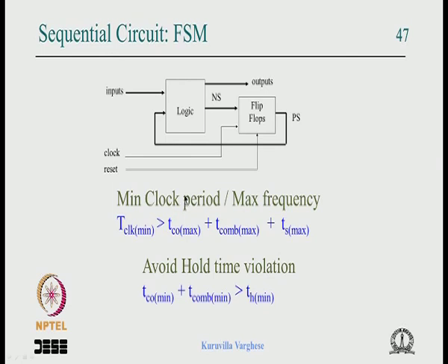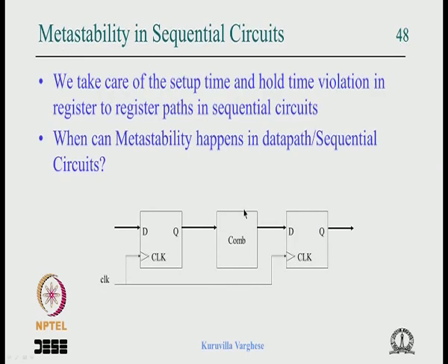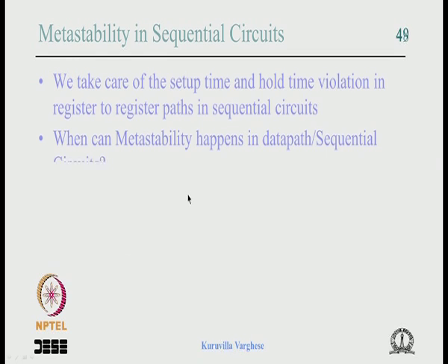Then why do we worry about metastability in a flip flop, because metastability happens only when they are violated? We take care of setup and hold time violation in register to register paths in sequential circuits and data paths, so when can metastability happen in a data path? That is the question.